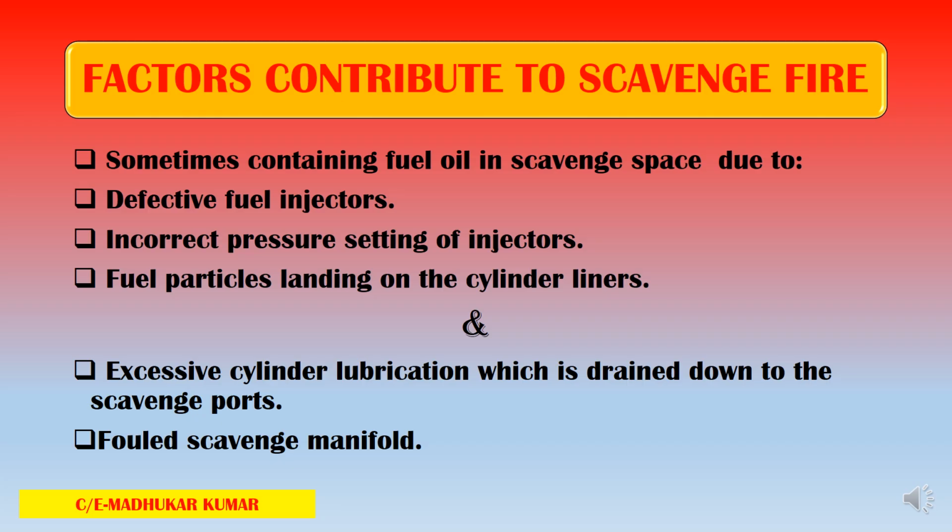Now, other factors are also associated. Sometimes fuel oil is present in the scavenge space, where defective fuel injectors are involved. Then incorrect pressure setting of the injectors, where the injection pressure setting is not correct, is also going to cause the collection or spillage of fuel oil in the scavenge space. Fuel particles landing on the cylinder liners, then the penetration, is going to lead towards it.